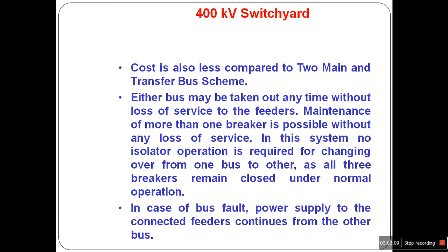The third advantage and the most important advantage of this scheme is in case of bus fault, power supply to the connected feeders continues from the other bus. So there is no interruption to the power supply of the loads.